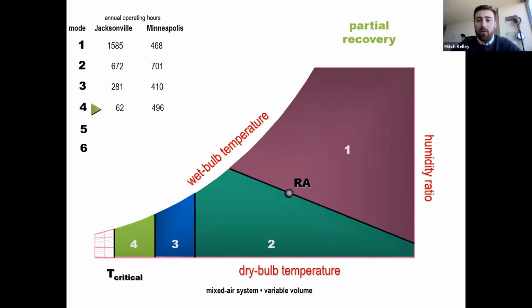In mode 4, the outdoor air is cold enough so that the outdoor air damper reaches its minimum airflow setting and the economizer is deactivated. The supply side bypass damper is now closed and the exhaust side damper is modulated, varying the wheel heat capacity to avoid overheating the supply air. Again, don't make the mistake of continuously operating the wheel at full capacity here. This would require turning on the cooling coils to recool this overheated air.